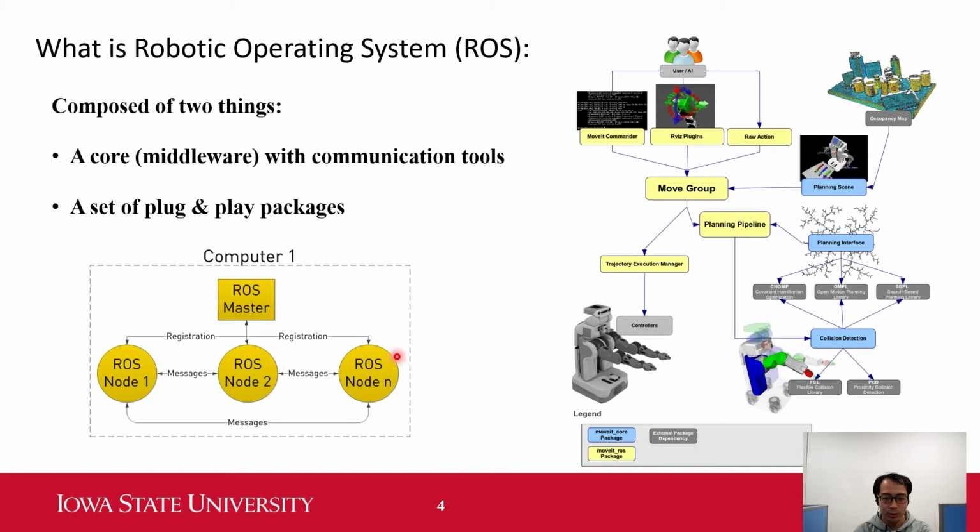In order to run the company, these workers need to communicate, share information, or pass material from one node to another. And under this ROS framework, there is a master, the ROS master. It acts as a router or server. It forms a local network, and with this network, each node can send information and pass material to the other nodes.